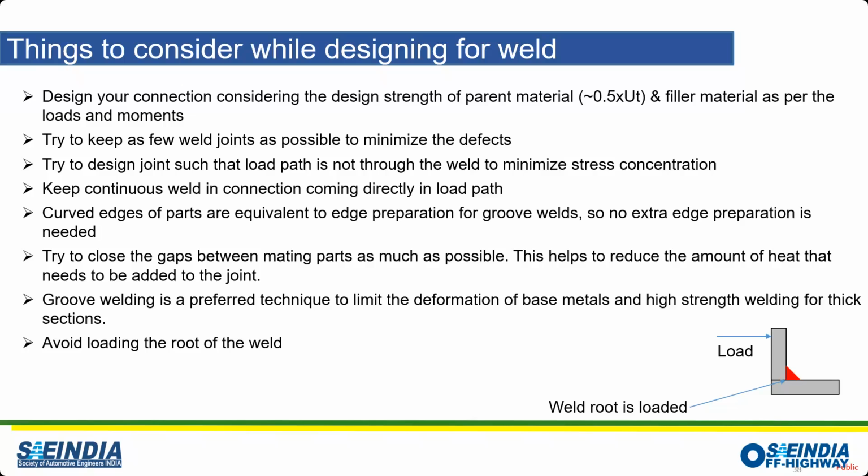What you want is that your material takes the load from one member to the other, and not the weld. The weld is just to keep the components together, but it is always preferable to keep your weld connections in tension or compression.